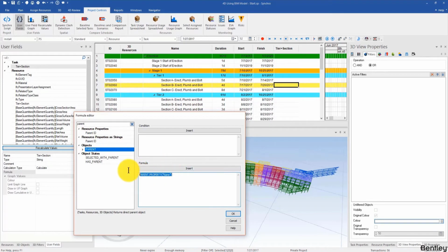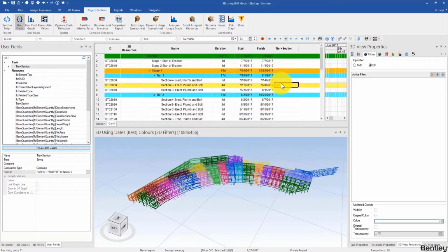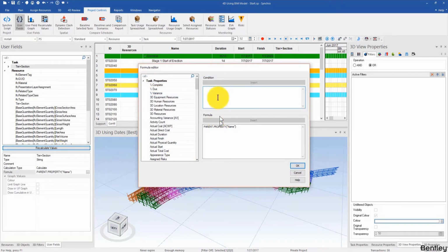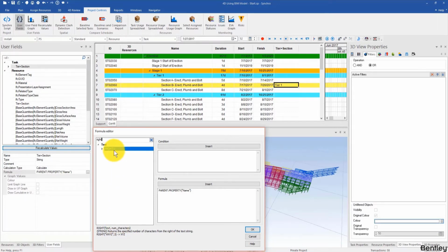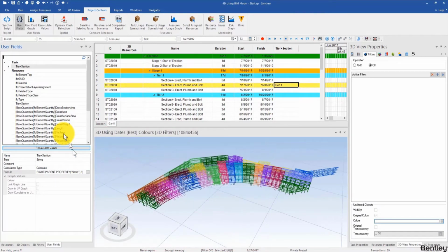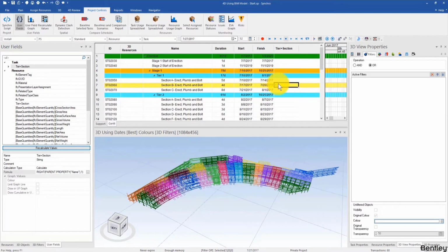So this is not enough. Oh, well, maybe let's take a look. So if I hit recalculate values and then uncheck all of the options, you can see I successfully got tier 1 already. So I just need to further work on this part so that I'm only getting 1 from tier 1, right? So in that case, I want to introduce another text formula, which is called right. Okay, so if I insert right now and then copy my tier 1 in there, and then typing 1 because I will be extracting from the right hand side of tier 1 and then with 1 character. So if I hit OK and then hit recalculate values either here or there, let me adjust the settings. Okay, you can see I've successfully got 1.